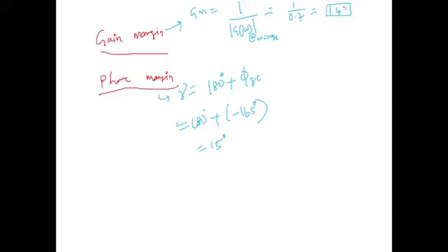So now this is the gain margin. If you want to find the value in dB, you have to use 20 log of 1.42. So 20 log of 1.42 is 3.04. So that is the answer, 3.04 dB, right? So this is how we have to proceed with the problem. Thank you.